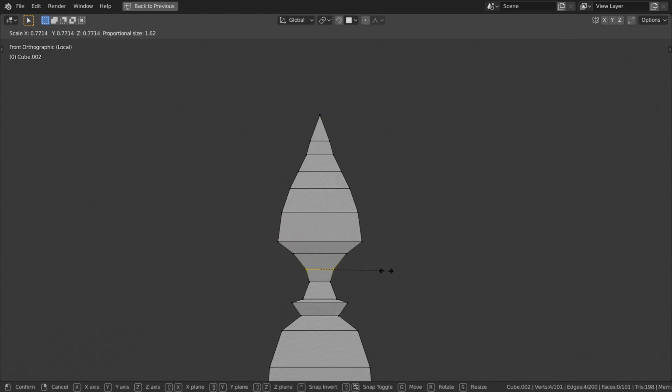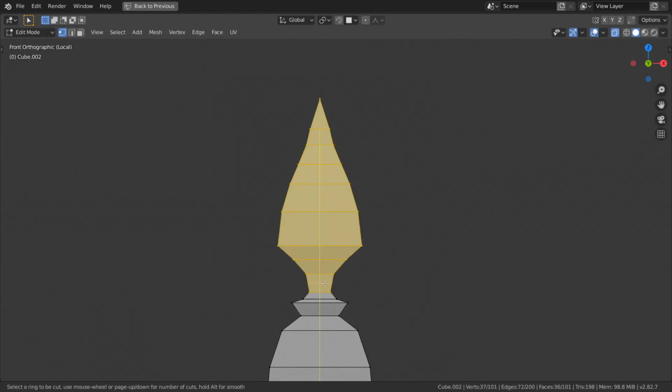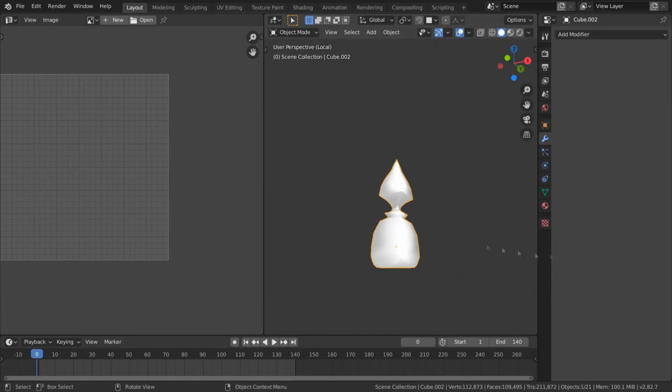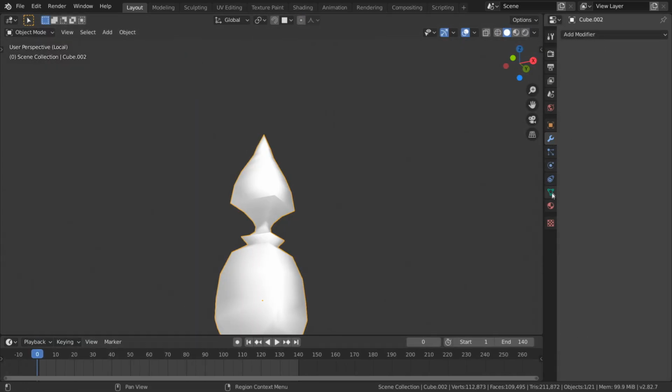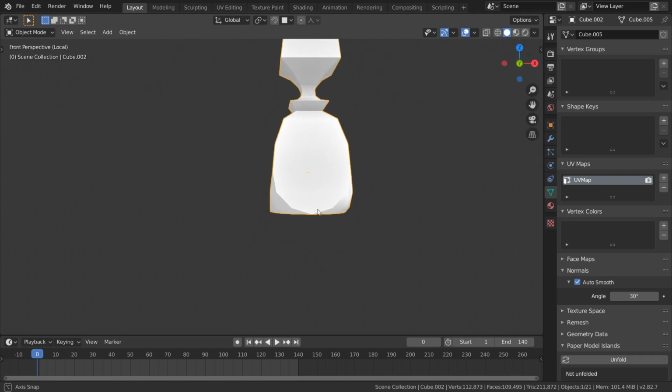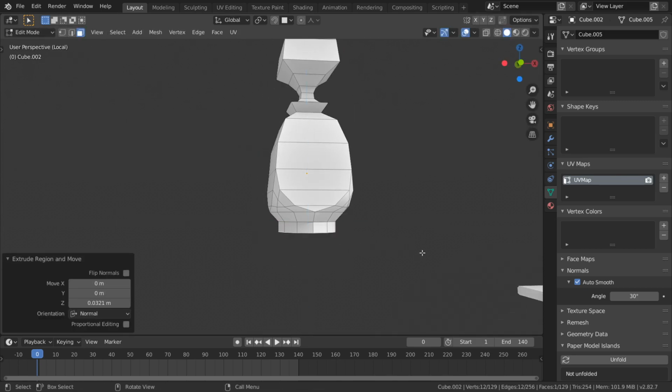Once the dolly is set to smooth shading in object mode, it will become very ugly since it lost all its sharp edges. Go to Object Data Properties and turn on the Auto Smooth option to get the edges back.